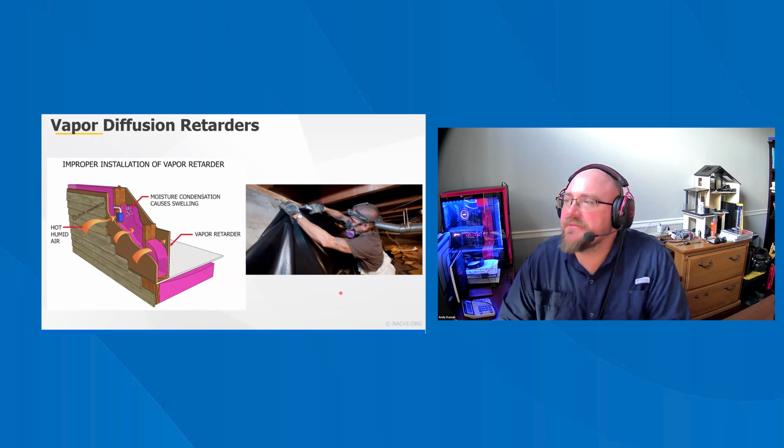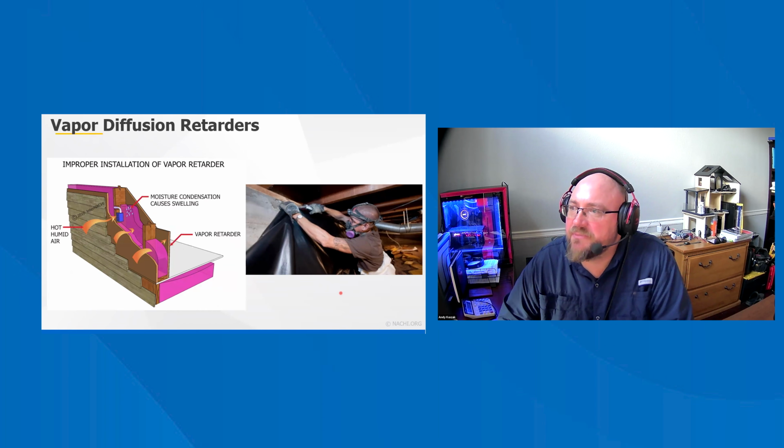The amount of vapor diffusion that occurs in a building is determined by two things: the driving force that pushes it, known as the vapor diffusion differential, and the permeability of the material the vapor is passing through. Most materials, even glass, are unable to completely stop vapor diffusion. Thus, calling something a vapor barrier is a bit of a misnomer.